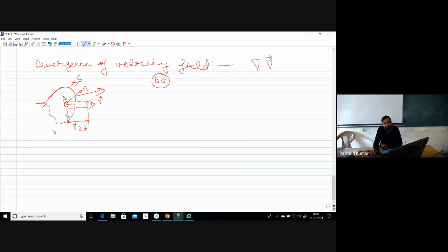While a fluid element of fixed mass is moving in a flow field which has variation of flow properties with space, the volume of the fluid element will change at different locations. Say it enters a location where density is high, there it will shrink, and if it enters a spatial location where we have low density, there its volume will expand.